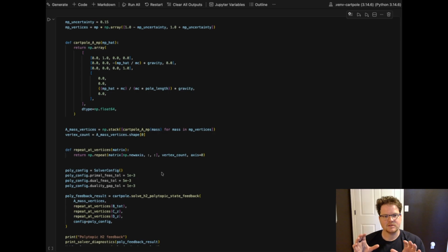For this scenario here, that's not the case. We can actually pump up this uncertainty of the mass of the pendulum even more if we want, and then relax these terms a little bit better. The mass of the pendulum is significantly lighter than the cart. And then likewise, the dominant pole that we walk through in this notebook is associated more with the pendulum control, right? It's much more controllable than the cart.